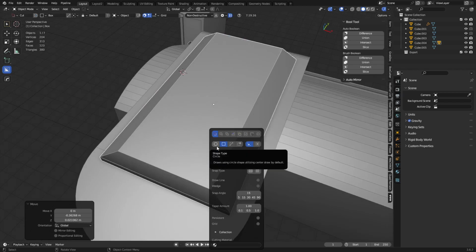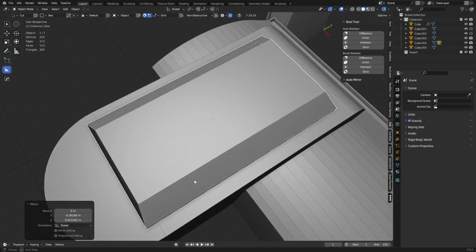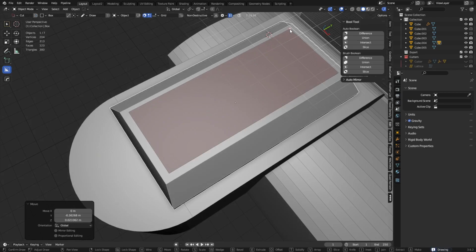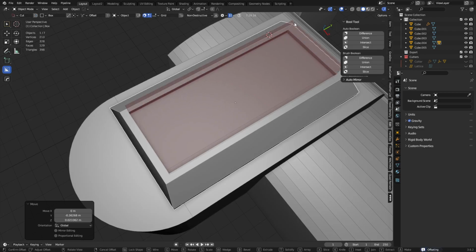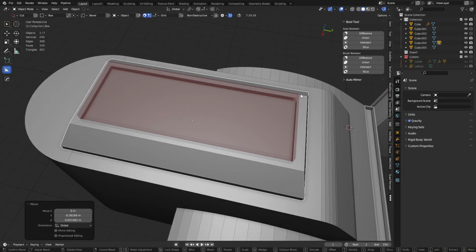So when we hold control here, you see the grid doesn't line up to it exactly perfect. But we are going to use a 10 centimeter grid just by holding shift. And so if we want to cut the same kinds of cuts that we had on the other one, or similar anyways, we'll get a very similar result out of it like this. So we might need to hit E or E again to flip back and forth between these two. We could do bevels, click once. We could do bevels by grabbing each corner and middle mouse clicking it. This is going to use a weighted bevel, which is fine if you want to do that.